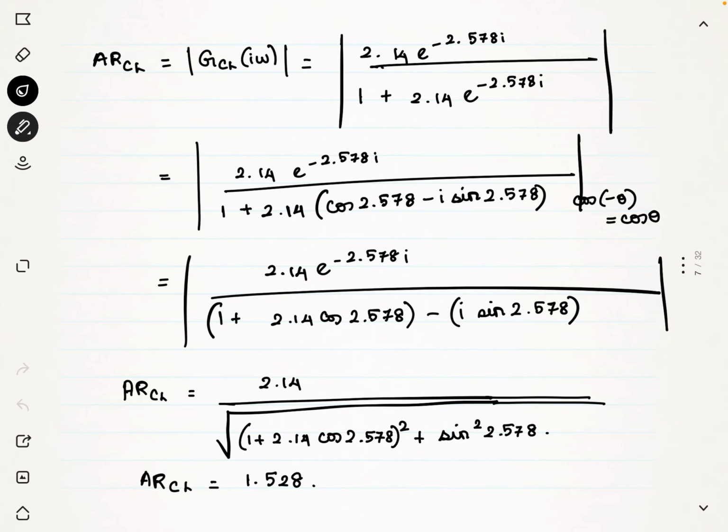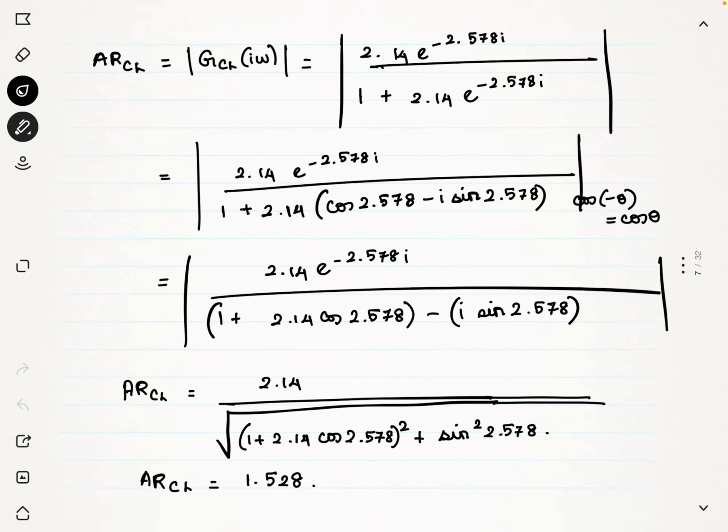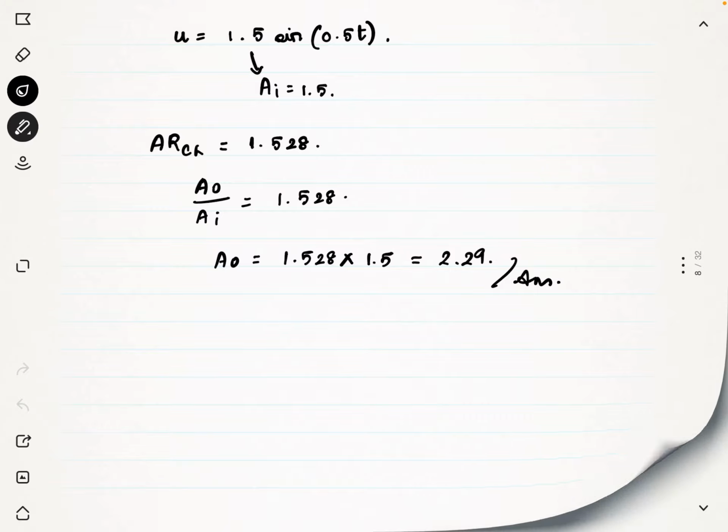Yeah, the closed loop was slightly tricky because we had to write the numerator and denominator in polar coordinate form to make our computations easier. Otherwise we'll be having lengthier equations and it's really hard. And also if we write it in polar coordinate form, we can use the numeric values we have computed from the previous steps from the open loop conditions and substitute those values. So it has simplified our calculations to a greater extent. This completes question 1, and now let's go to question 2.